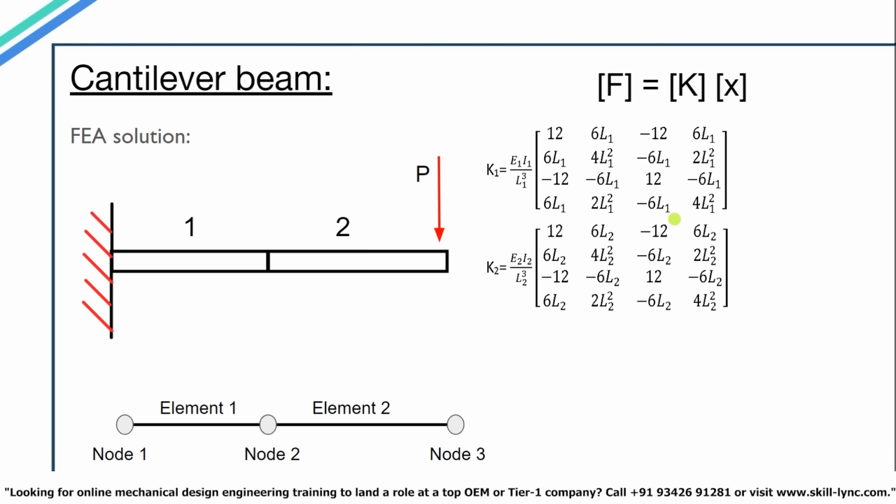First, the stiffness K is found for each of the elements using a formula similar to what's shown on the screen. Using these individual stiffness matrices, the matrix for the entire beam is formed, which is known as the global stiffness matrix. Then, by using the basic relation previously shown, the displacements for the beam are calculated. In the displacement matrix, you can see 2 types of variables used, V and theta.